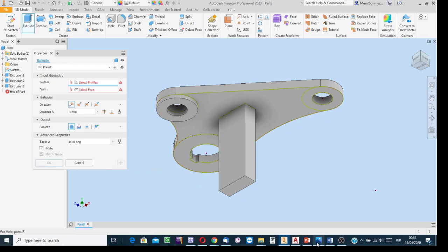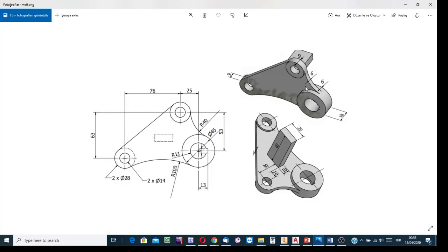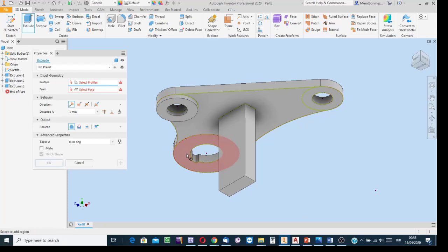Here on the same side, we have a boss. Sorry, this one, a boss. See its thickness, shown over here as 6. Then apply the process. If the software were AutoCAD, we would draw these circles. But in Inventor, we can use the same sketch n times.